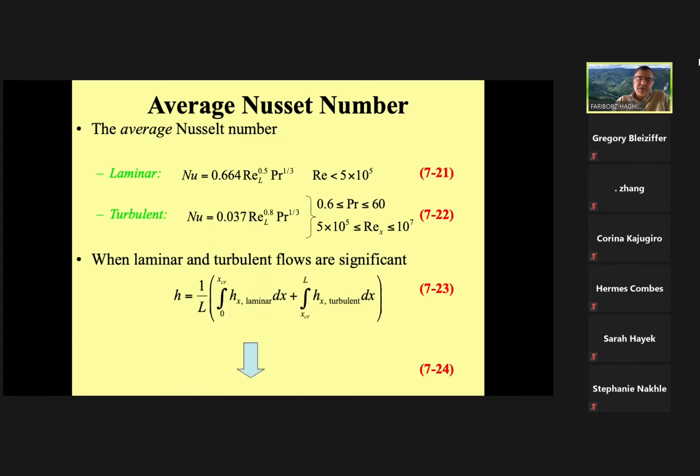And we mentioned for the case that we are not sure, because as I mentioned, you have a 1 meter plate, probably 40 centimeters laminar, 60 centimeters turbulent. Therefore, in order to take into consideration both physical phenomena, we can use the equation from 0 to x, the critical value, where we consider laminar. From there, we can assume this one. Therefore, this equation is for a small plate, where the laminar component is as important as turbulent. But if you're dealing with something 10 meters, 20 meters, and you can see only the laminar portion is very small, we can go back and use this equation.